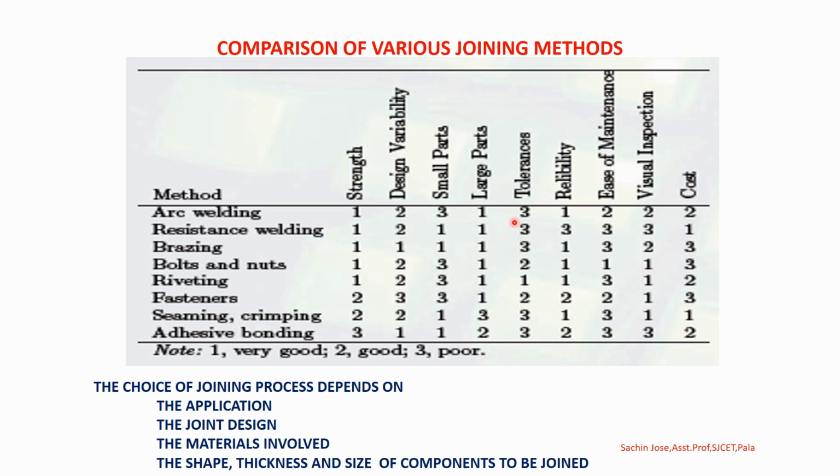Tolerance is not so good because you are dealing with a heavy voltage electrode, and it all depends on the workman's skill to get high tolerance levels.